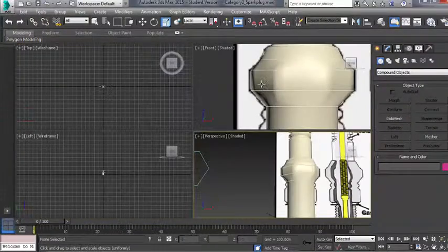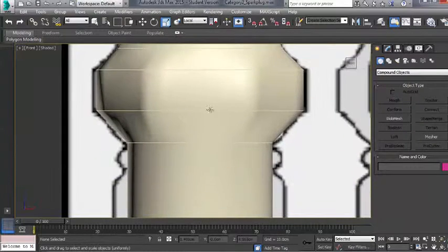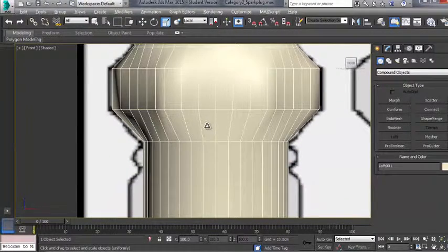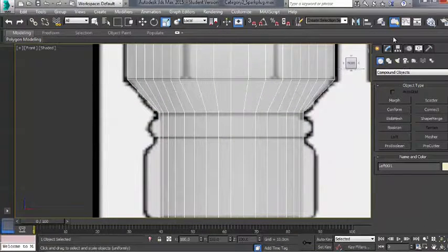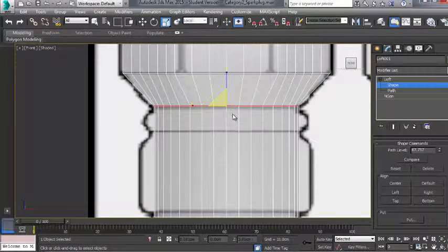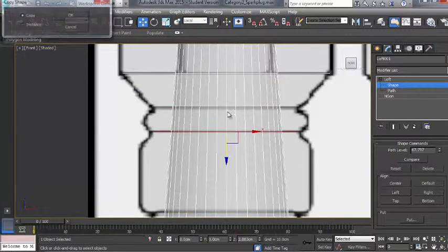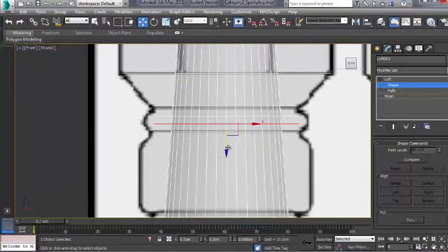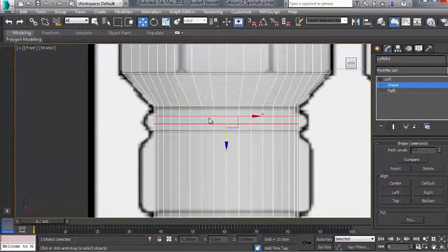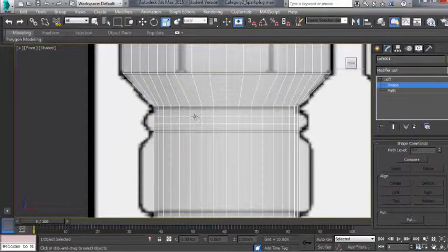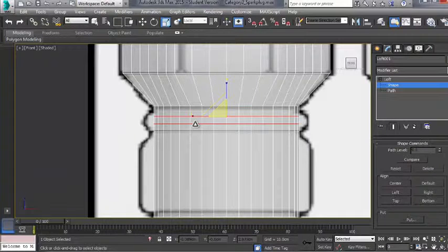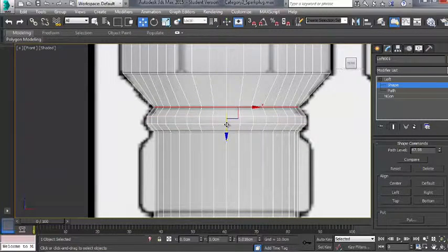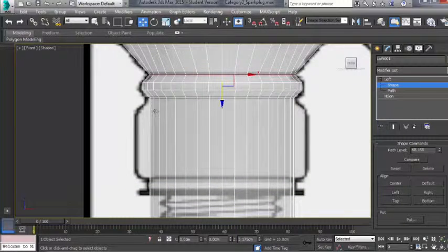So just go back into the front view. I'm going to finish off putting that all the way down. So Alt X, I'll select the object, Alt X to make it go transparent. And again back to grab our shapes. Just drag that one down there. Get that bit in the middle. Both of those. To select multiple lines as well, if you click one line and hold Control and click the other line, that'll let you select multiple lines. Just neaten that up a little bit.